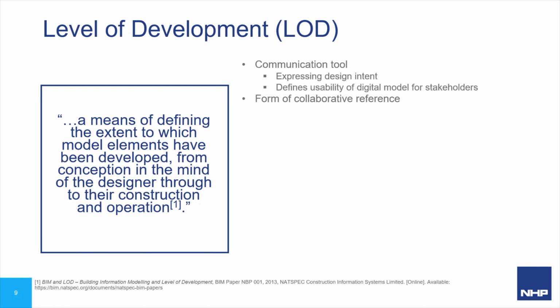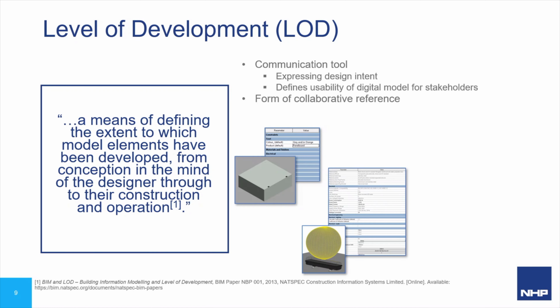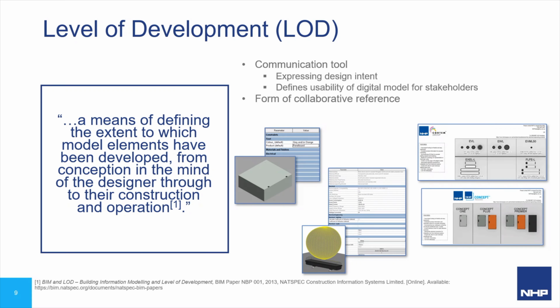Like BIM itself, LOD is also a communication tool. It can be used as a method to maintain a level of consistency between BIM objects, or it can be employed as a reference to which team members can measure to. BIM objects can also be developed at a different pace to one another, or at different periods in a project's timeline. The last thing you need is a breakdown in communication where you have one team develop a BIM object like this, another team developing like this, while at this point in the design phase, the project manager was expecting this.